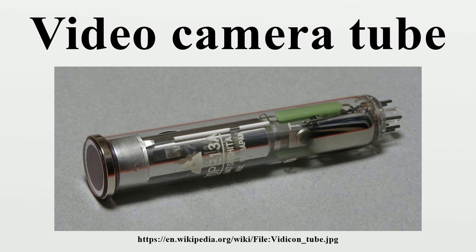The image dissector has no charge storage characteristic. The vast majority of electrons emitted by the photocathode are excluded by the scanning aperture, and thus wasted rather than being stored on a photosensitive target, as in the iconoscope or image orthicon, which largely accounts for its low light sensitivity. Iconoscope. An iconoscope is a camera tube that projects an image on a special charge storage